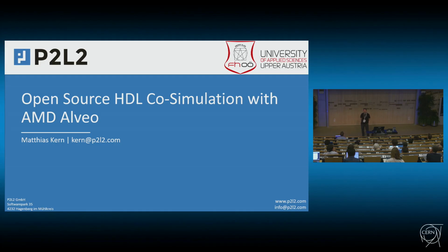You can. I run the design at 200 megahertz, and it does not matter because it just needs to be synthesizable. And if it meets the timing in the synthesis, then this does not correlate in any way with the actual frequency that the design is running at in the real hardware in the end. It's just like simulation. You can set the simulation frequency to a gigahertz, even if the design would never run at a gigahertz. So these frequencies are decoupled.